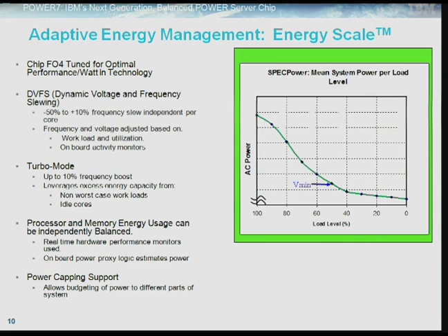The microprocessor monitors several on-chip counters to measure utilization of the system and varies both the voltage and frequency of the chip to provide a square takedown power curve. We continue then until we reach voltage minimum, at which point we continue with a linear takedown curve scaling chip frequency.